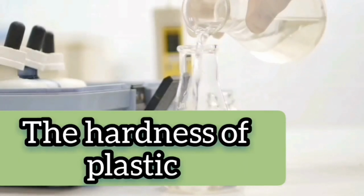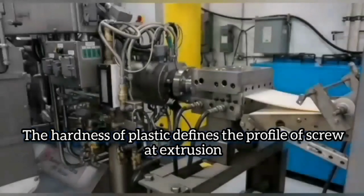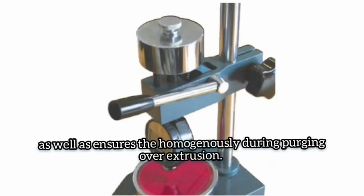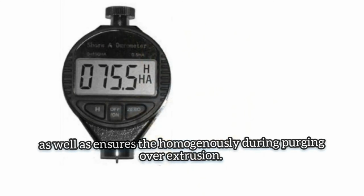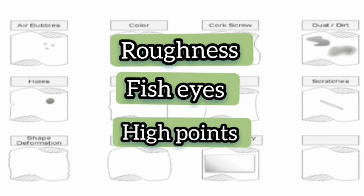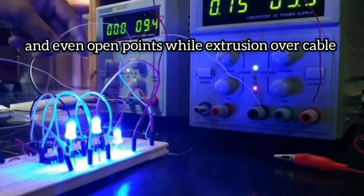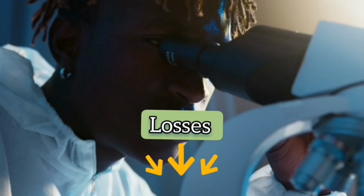The hardness of plastic: the hardness of plastic defines the profile of the screw at extrusion as well as ensures homogeneity during purging over extrusion. If this is not according to the specifications, you might feel some roughness, fish eyes, high points, and even open points while extruding over cable, and might consequently have to stop the machine, resulting in downtime and losses.